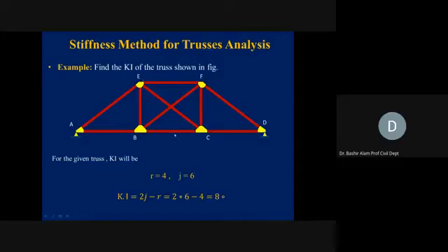If we want to find the resultant of these, what is the solution? We resolve them into rectangular components, horizontal and vertical. This horizontal and vertical, which is the same for all the members, we call the global coordinate system.